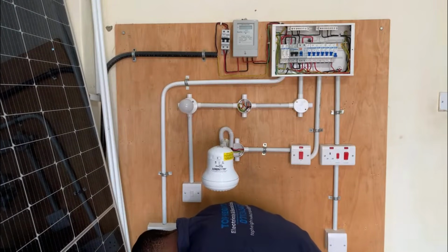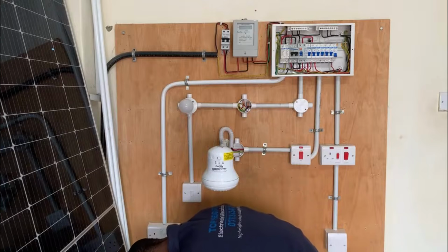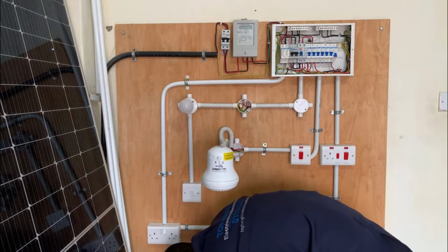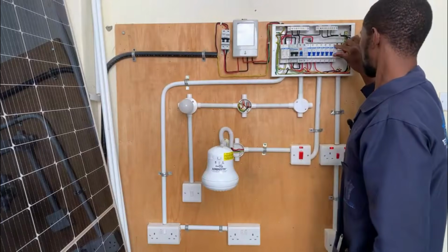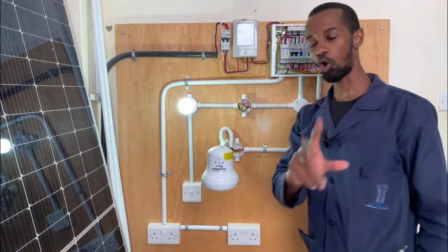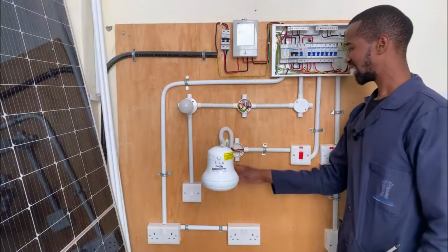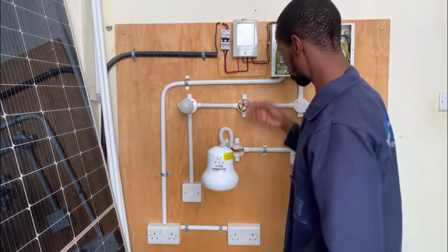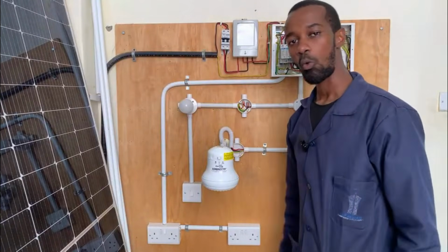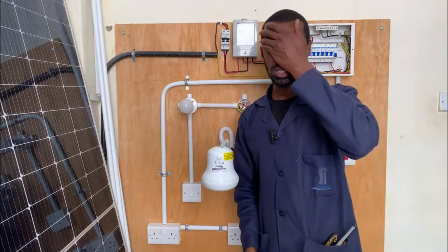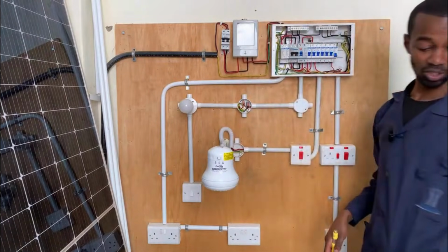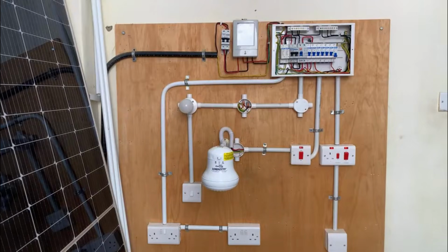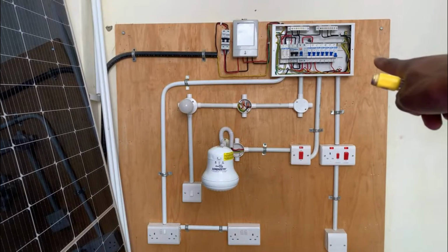Okay, so if you are struggling with the basics, then electrical troubleshooting will really disturb you. You will have a huge challenge. Power is flowing in here, the light is on, and the customer has called you and told you the light is off. I've been trying to switch it on, nothing is working. Do you go ahead? At this point you have to suspect that something has tripped, and true to your suspicions, there is an MCB that is down right there.